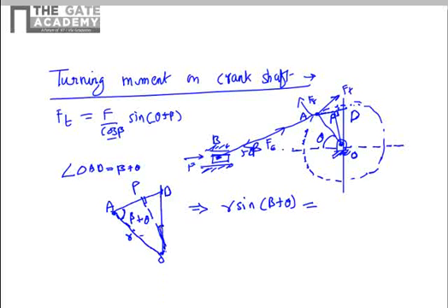cosine of this angle. So now this is a horizontal axis, this is a connecting rod. The connecting rod makes an angle beta here, and this is a straight line. BAD is a straight line. Since this angle BOD is 90 degrees, this angle will be 90 minus beta. Now since this angle is 90 minus beta from this right triangle OBD, we can determine this angle also.